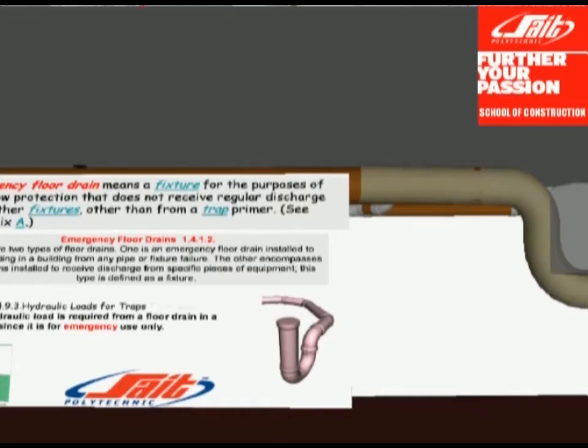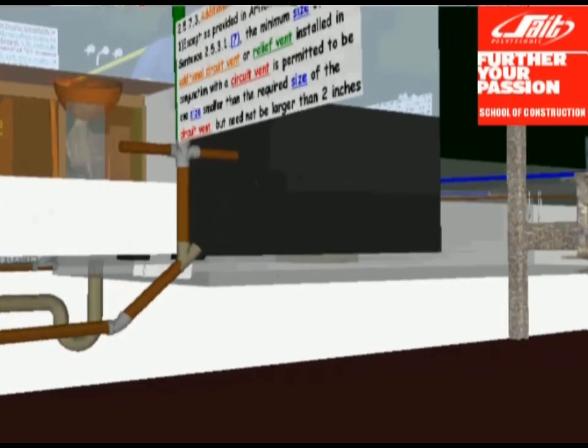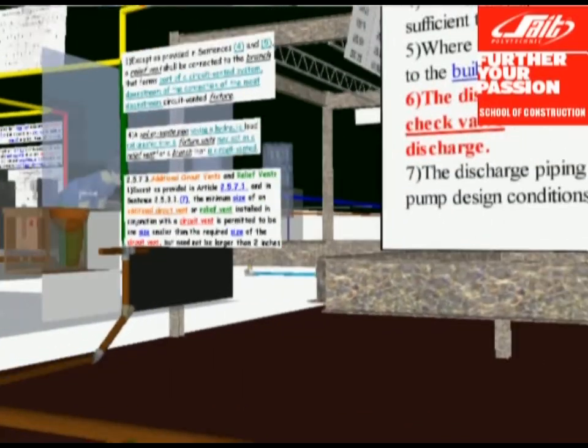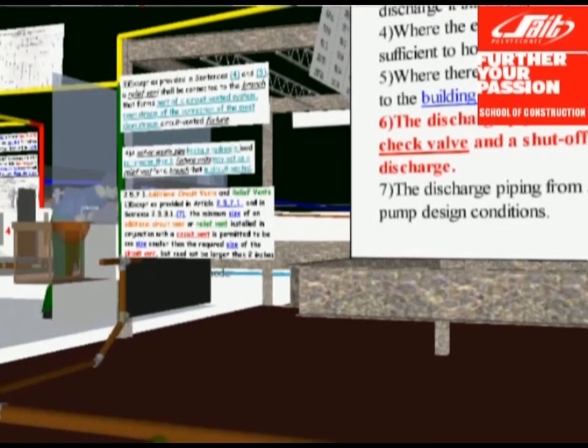This last green vent, which is venting the 2 basins, is our alternative relief vent. You can use a separately vented soil or waste pipe that has a hydraulic load up to 6 fixture units as your relief vent, as long as it is the most downstream connection from the most downstream circuit vented branch fixture. The brown pipe or branch beneath the vent must be sized according to the branch table.